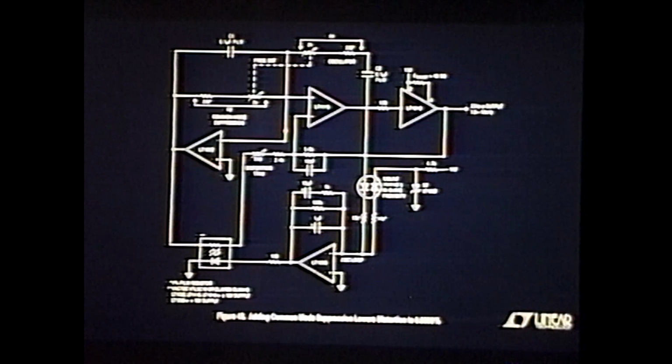I don't have to match any gain. I don't need any resistors at all. It's free. This amplifier is going to do whatever it has to do in its single-minded pursuit to force this input to 0. And the rest of this loop is just going to all follow around that point. When you do that, if that's at 0, then that must be at 0. This end of the bridge ends up at whatever negative swings it has to satisfy this.